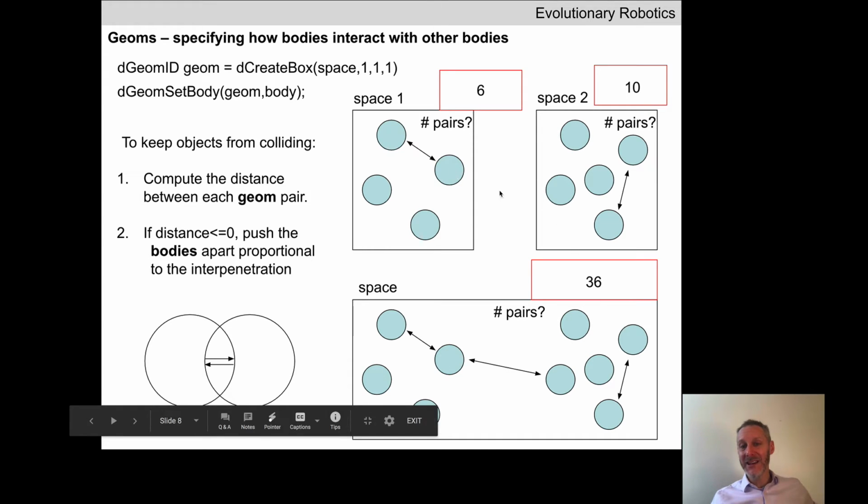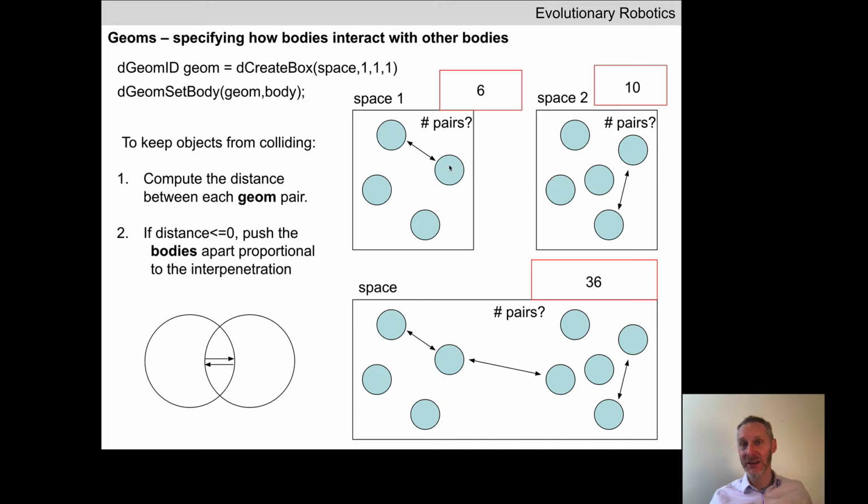There is one additional comparison we need to do here, which is whether the bounding box of space 1 and the bounding box of space 2 are colliding with one another. So we need to do a 17th comparison. What do you think we need to do if it turns out that those 2 boxes or those 2 spaces are actually colliding with one another? What happens if we detect a collision event in the 17th pairwise comparison between space 1 and space 2?